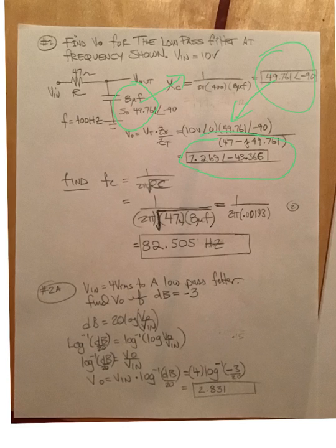Very straightforward. If I wanted to find the critical frequency, I could, but again, I got the wrong formula here. You need to get rid of that square root, and that's obviously going to give you a different value here. But while you're doing your homework, they're going to ask you to make this calculation, so you might as well have 1 over 2 pi RC written down correctly on your formula sheet.